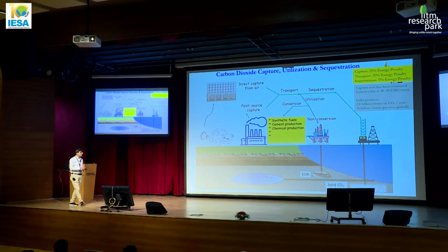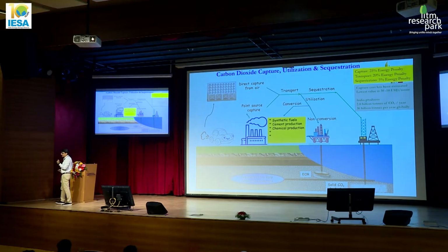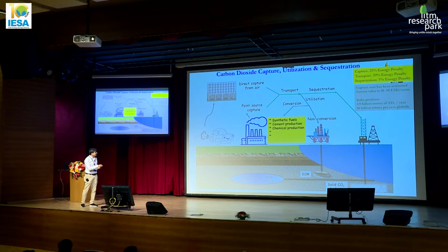So basically it's important for you to understand, if you can avoid a chemical reaction between this solvent and the CO2, it's always better. Go for a physical solvent where there is no chemical reaction and regeneration is much easier. So you are not going to lose any material over there. So the advantage over here is obviously in terms of cost, in terms of CO2 emission, because the amount of material which I am going to need over here will be not 10 times of this, but only twice of this. Okay, so that's the advantage. I am not producing as much CO2 over there.